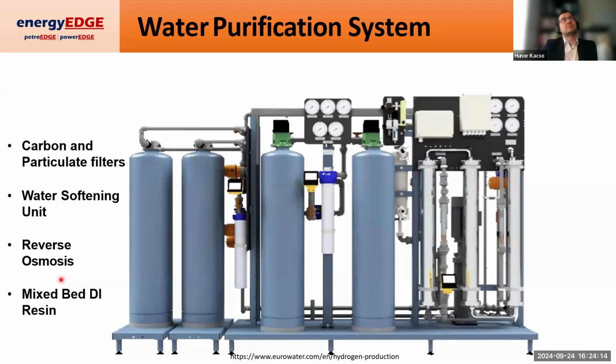Depending on what you read, some people tend to think that PEM electrolyzers can basically get away with water conductivity of about 5 microsiemens per centimeter. This is wrong. The lower the conductivity, the better for the stack.